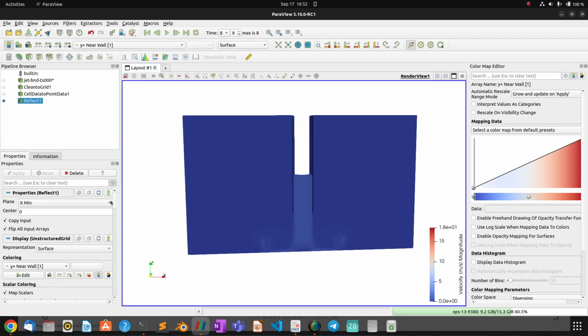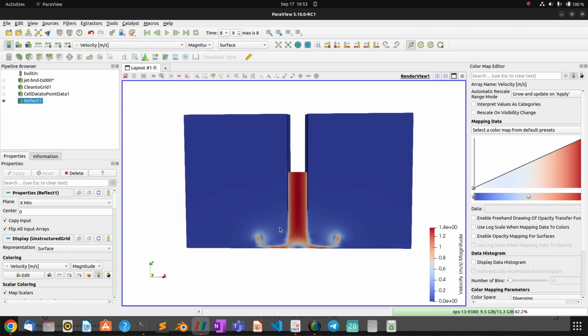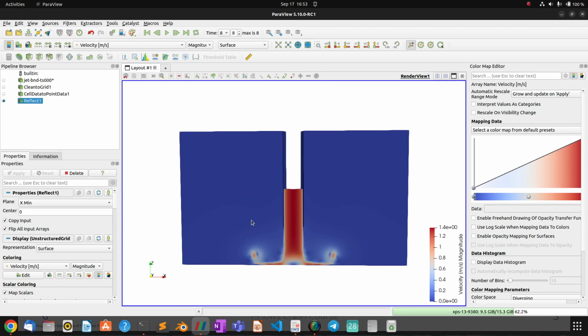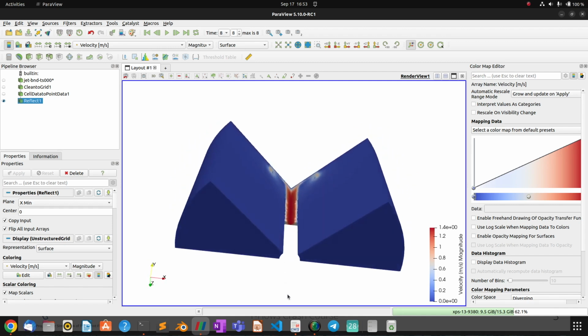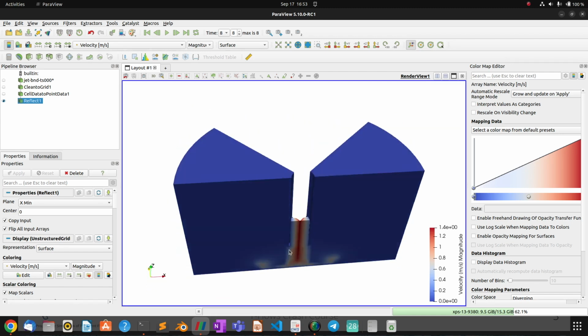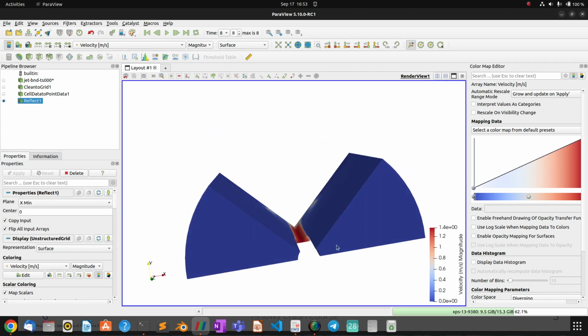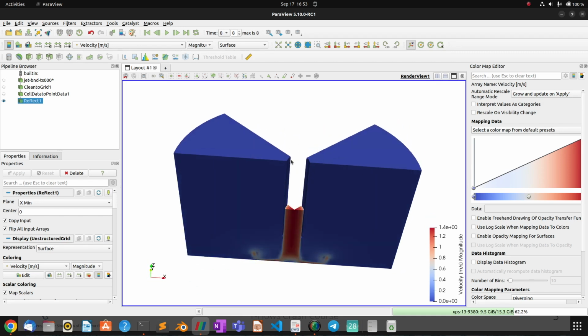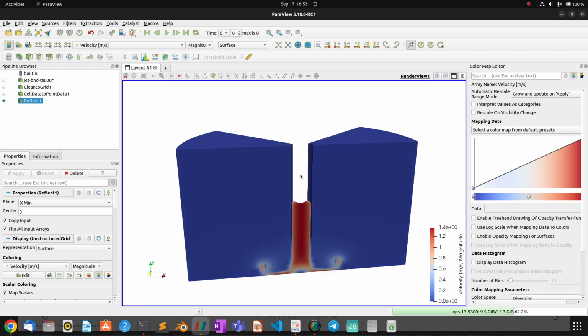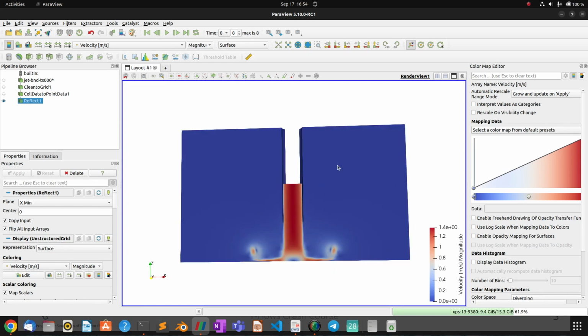And if you visualize the domain again, you can see that the flow was intended to be a cylindrical flow. If you visualize the velocity field, you can see it's an axisymmetric flow, but we just took this part of the domain to reduce the cell count. But you can always reflect, and it's a more representable picture of the flow, and then it's of course completed here. So with this cylinder, you now have more of a 3D effect of what's happening, if you like, but that's just an option that I wanted to show you. It's basically just copying what happens on the right domain and mirroring it across the axis.